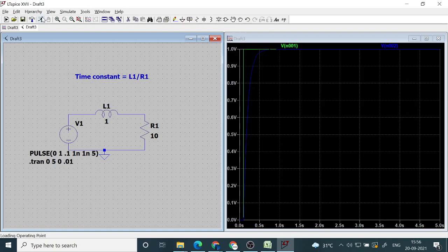Okay, is it clear? Yes, sir. Okay. So here the time constant is L by R. Earlier it was R into C. Both are first order circuits. Now what is happening here? To see what is happening here, it is a good idea to look at this voltage also. So you see the voltage, what happens? The voltage is initially very large. Almost the entire applied voltage, 1 volt, comes across the inductor, and then gradually that voltage reduces and reduces.